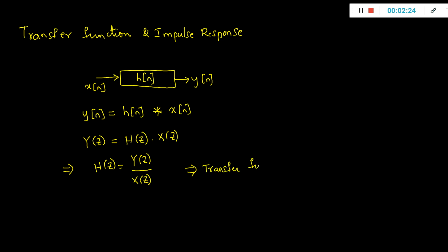And if I take its inverse z transform, it is going to get me h of n. So the point is, if h of z is given to me, I can find the impulse response of the system very easily using this particular type of analysis. Let's try to see some examples in the next video.